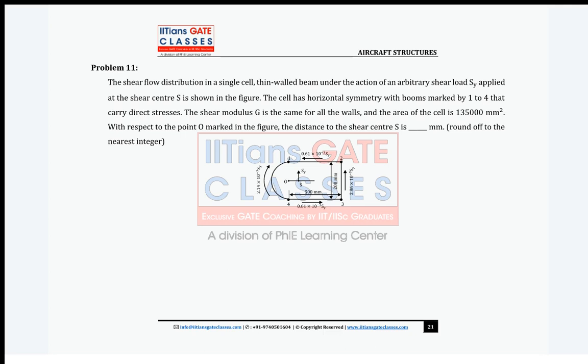But in your GATE exam, I think in a magazine book, you can see this kind of question. Suppose this is the question and you have to find shear flow for an applied shear force. What you have to do is make a cut and then solve it as an open section. Then this unknown q naught you have to find using your torsional shear flow part. Yes or no? Has anybody done this exercise in your engineering exam?